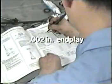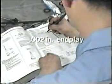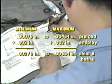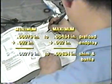Let's try an example. If the end play measurement is 2/1000ths of an inch, add the minimum and maximum preload measurement from the manual to the existing end play to calculate the combined size of shim and baffle, which would be acceptable. Since preloading the shaft and bearing puts them under pressure when the case is reassembled cold, select a shim and baffle size nearest the minimum measurement to reduce noise.